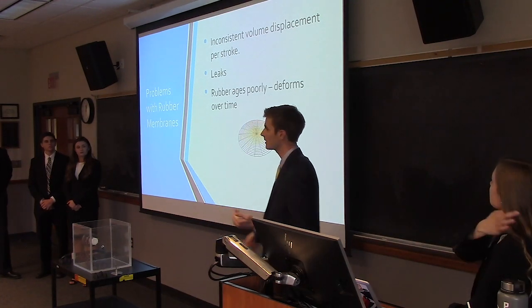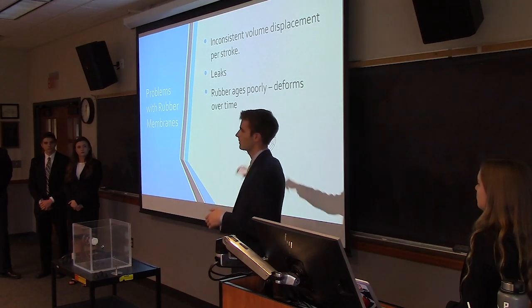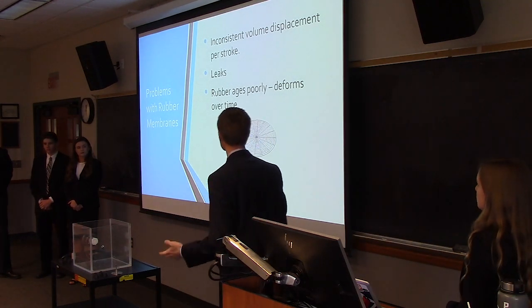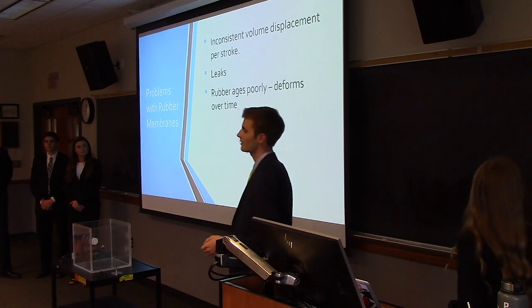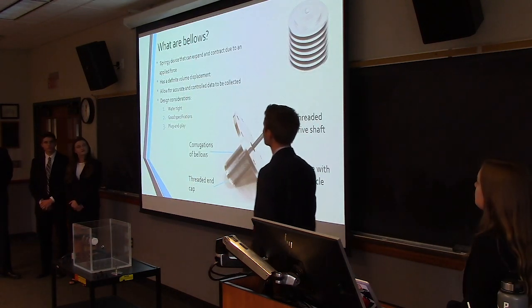The system also leaked. This rubber wasn't perfectly watertight, and through the center, there was a drive shaft, which would sometimes leak, especially as it aged, because this rubber did not age very well in seawater. So we looked into bellows.